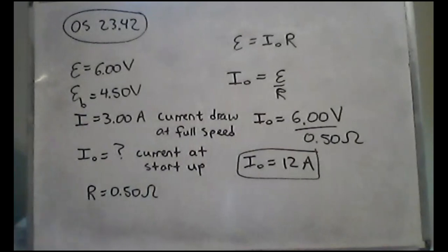That's before the motor is fully developed and at its full speed and the back EMF is fully developed. The initial current I need to draw is very large at that point. All right, that's the concept of back EMF. Now we go to the next topic.